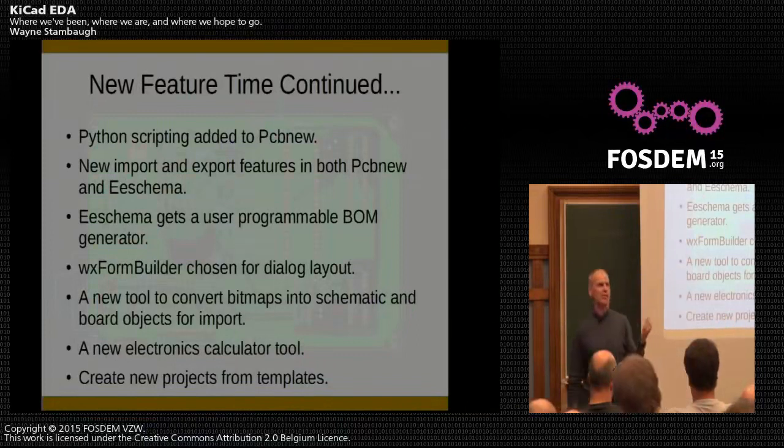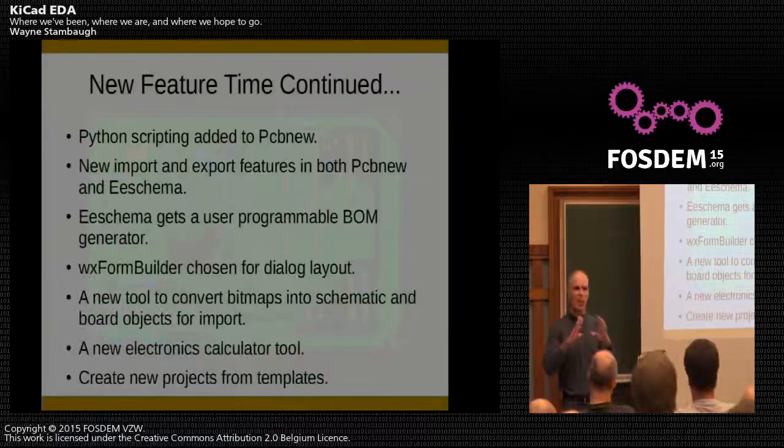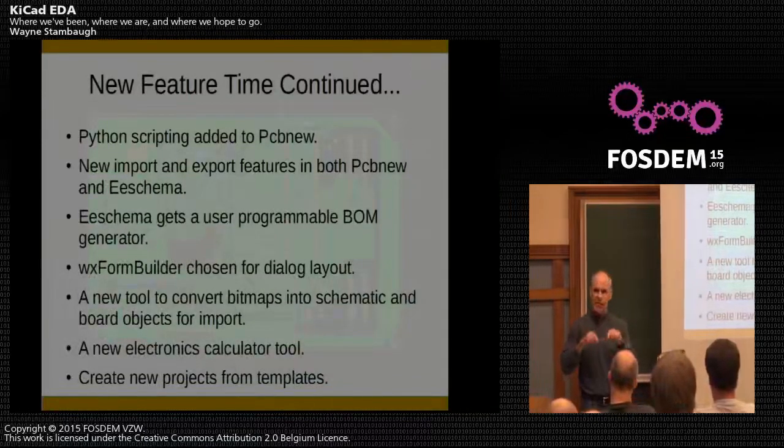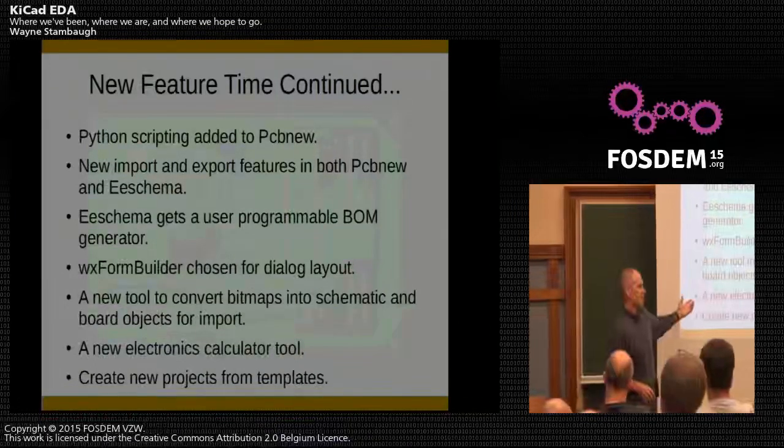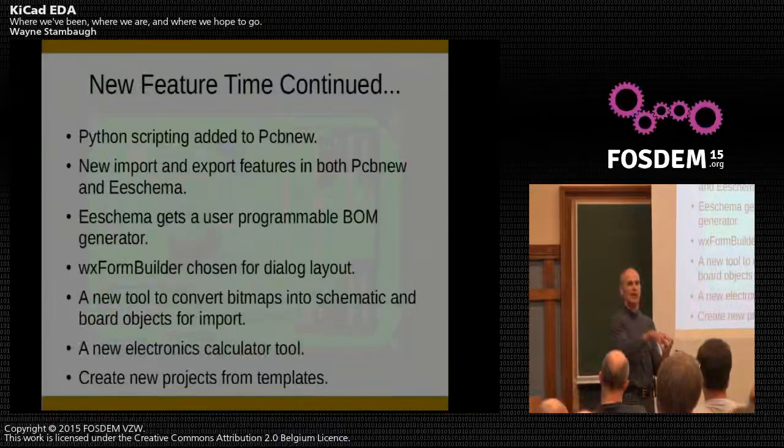And then we added templates. So there's quite a few templates, like some of the standard form boards, like the Stellaris standard form boards. There's a board layout with all the I/O in the correct place, and you want to do a project with that board. Say you want to make a daughter card to mount to it. You just suck that in. Everything's in the right place. The holes are in the right place, and then you can lay your schematic out around all the existing stuff.